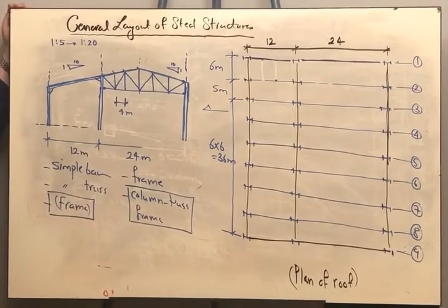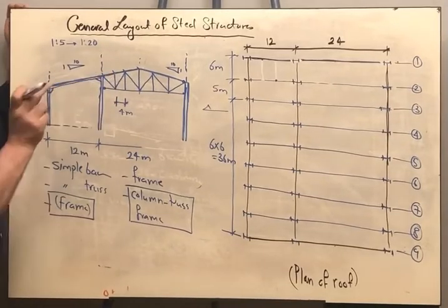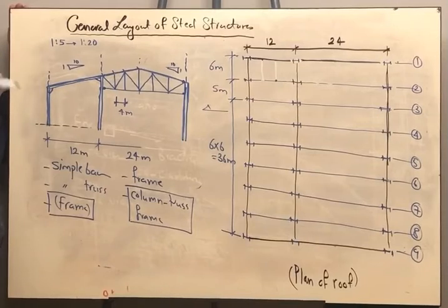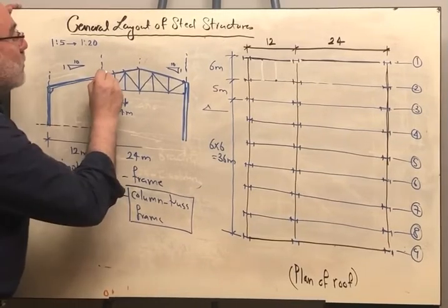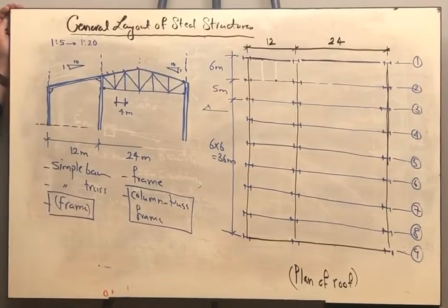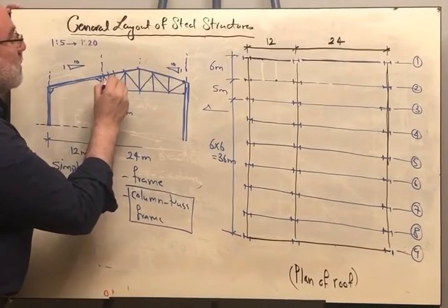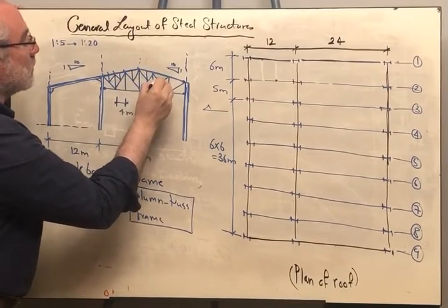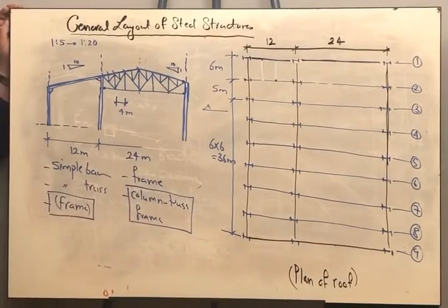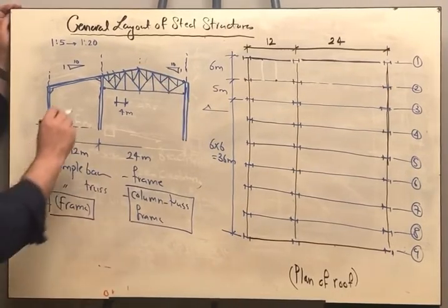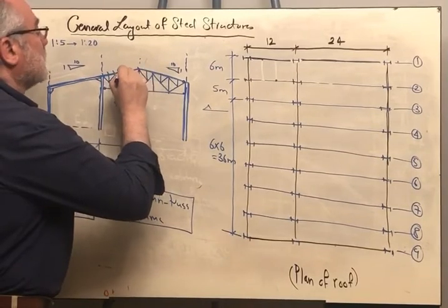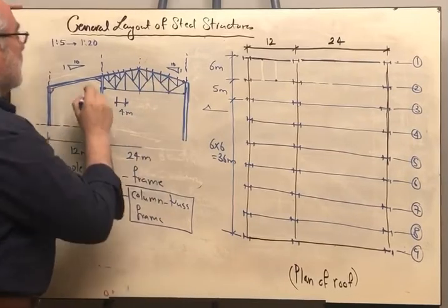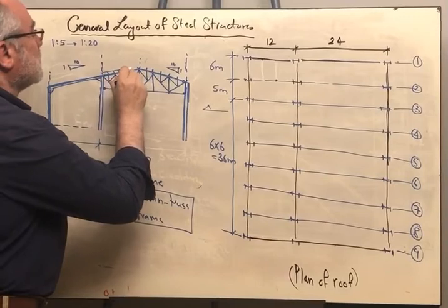That's a lot. Because as we said, the spacing between the purlins should be between 2 and 3 meters so that the cladding system is not that thick and is not that heavy. I need to have another purlin in the middle. How can we do that? We have to provide a subdivided system. We have to provide another joint in the middle, in order to reduce the spacing between the purlins. The purlins will be located like that. And here I'm having the roof cover.